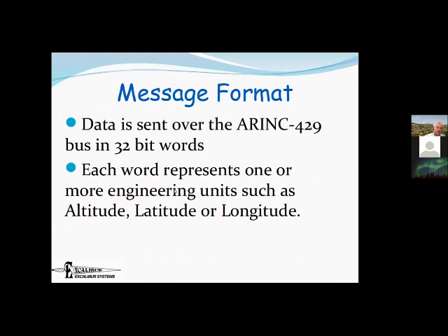Okay, message format, once we've determined how we keep you from colliding, which is by only having a single transmitter. So the data itself for ARINC is sent in 32-bit words. ARINC-429 is not really designed for sending large amounts of data. There is, in fact, a part 4 of the spec that talks about the Williamsburg protocol, which does allow you to send files, but ARINC really is not an efficient way to send files. And we haven't come across a lot of people who use Williamsburg.